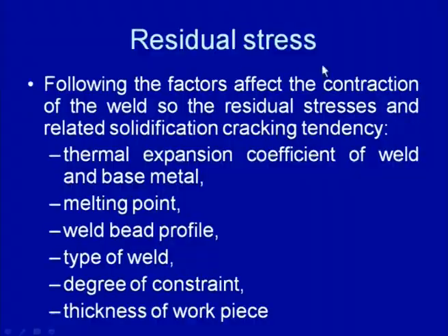If the weld metal has poor properties at high temperature, in the form of limited ductility and low strength, then under the tensile residual stresses the weld metal tends to crack. So, it is desirable to have a reduced magnitude of the tensile residual stresses set up in the weld zone, while the weld metal has reasonably good ductility and strength even at high temperature. The following factors affect the contraction of the weld, and so the residual stresses, which in turn affect the solidification cracking tendency.